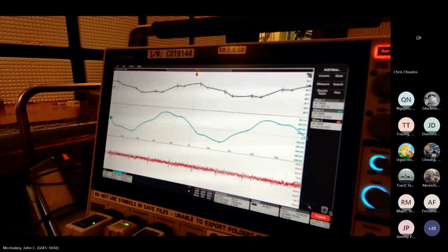Question? Yeah, a remark. It looks like current leading voltage by about 90 degrees, so you're well capacitive now. Yeah. Right. When you look at that phase relationship between the current and the voltage, you'd be able to tell whether the load looks dominantly capacitive or inductive. So yeah, thank you, Ed.